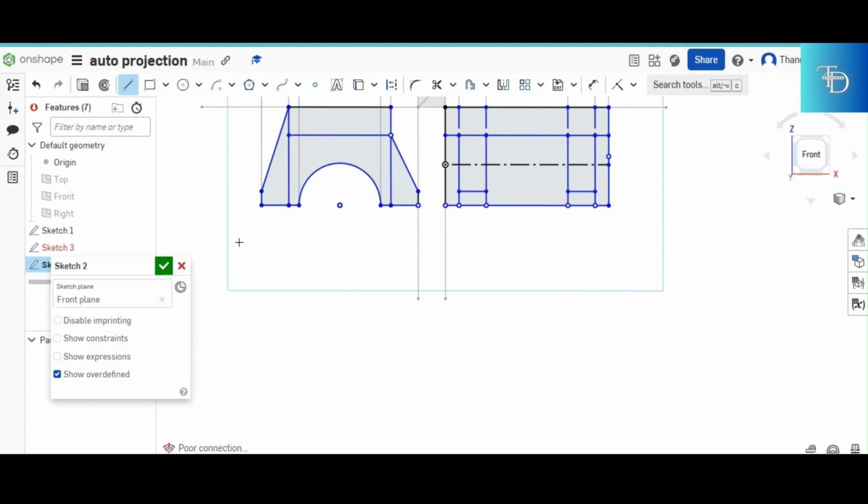In first angle, the top view is going to start from that corner. You have your front up there, and then a left view up there. I'm doing this to show you where your 45 is going to start when you are doing this in first angle. Your 45 is going to start exactly at that corner right there.